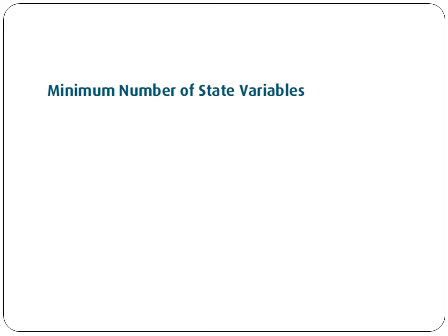So now we will discuss the number of state variables. How many state variables should there be? The number of state variables is always equal to the order of the differential equation. If it is a second order equation, then the number of state variables should be 2. That's it. If it is third order, then it should be 3, like that. And we can also determine that from the order of the denominator of the transfer function. From the order of the denominator, we can find the order of the system.